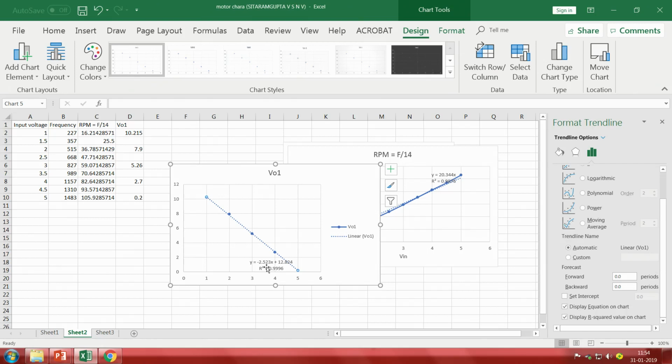So, when we do an integration, which is nothing but the area under the curve, the magnitude is higher when the RPM is decreasing, as the duration of the 15 volts becomes higher and higher because of more pulses. So the positive magnitude is higher compared to the negative, resulting in a decrease in the output from the integrator. We can even see that in this plot.